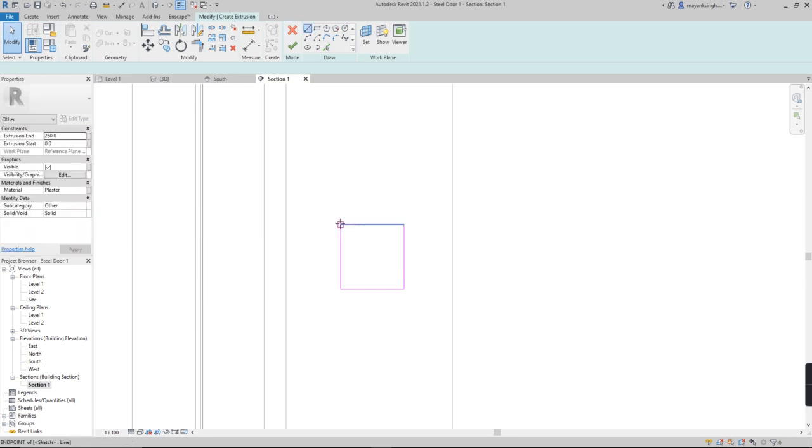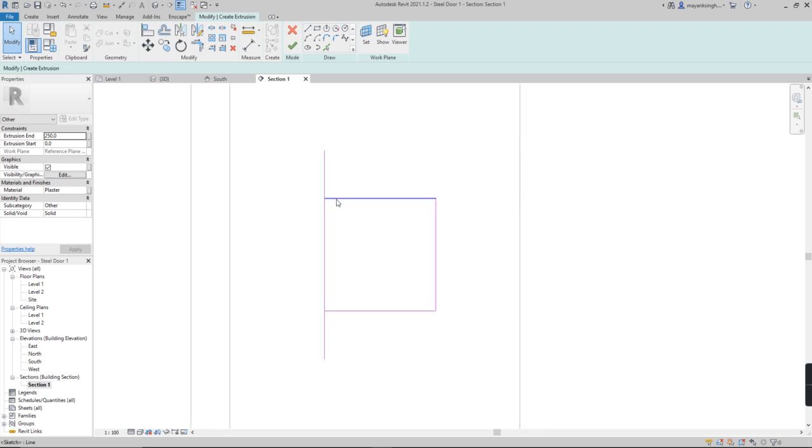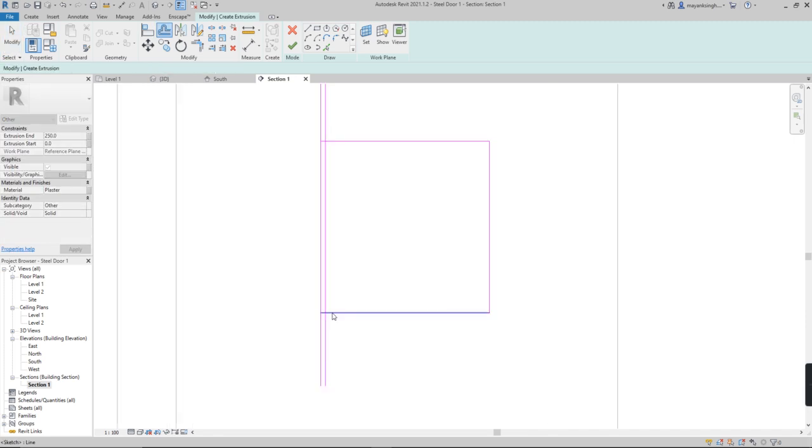And I'm going to extend it 15 mm on both sides. So because we have shutter panel on the top and at the bottom, and I'm going to make an offset of 1 mm here, and I'll make an offset of 1 mm by pulling this back first.